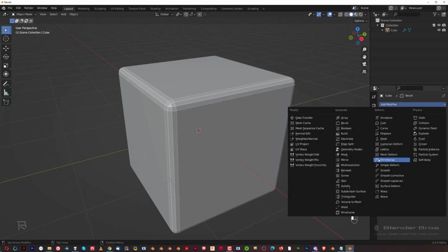A lot of them. But you're going to be mostly using 4 of them, okay? Bevel, boolean, solidify, and mirror, like 90%, guys, seriously. And of course weighted normal, so that's kind of an interesting modifier because this one usually runs on each mesh. We're going to be talking about it later. It simply fixes shading with bevels, okay, especially on boolean surfaces, so we're going to be using it a lot.